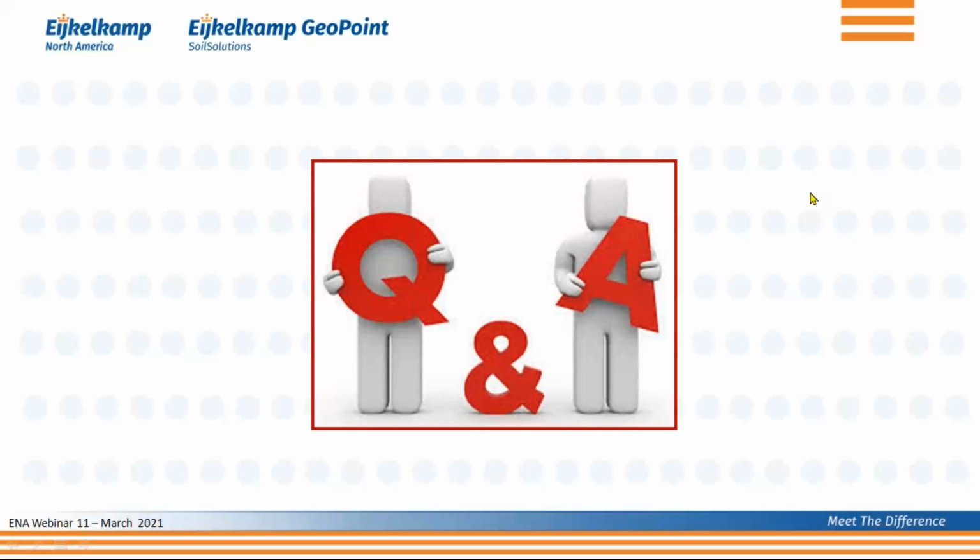And true, if you see very large particles, really large boulders in there, then obviously you need to stop almost straight away, because then you have a good chance that you're going to damage your cone as you push it deeper in the ground. But that could give you some valid information. So you need to weigh what you're trying to do, and there's not necessarily a very straightforward answer, but think about what you really want to get out of this whole thing before you get started with it.